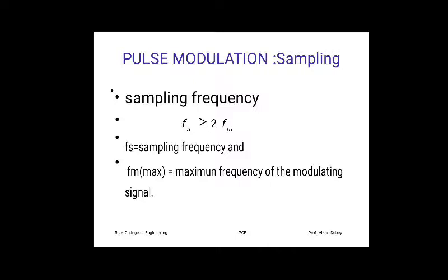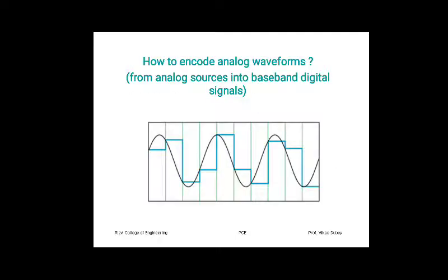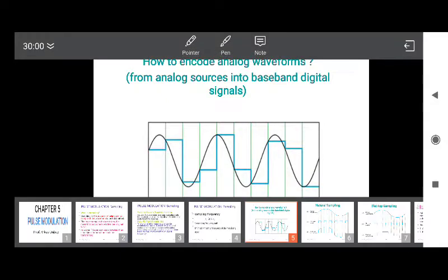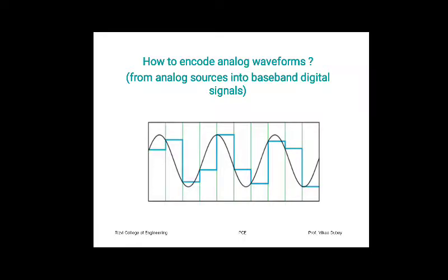Now, we have seen there are three types of sampling. Here we can see how the sampling is performed. In black color it is an analog signal, which is also called a baseband signal, and then we have square pulses which are going to multiply it. If you see in this diagram, in one cycle from peak to peak, the number of samples are 1, 2, 3 and 4. So 4 samples are there, which means Fs is 4 times Fm.